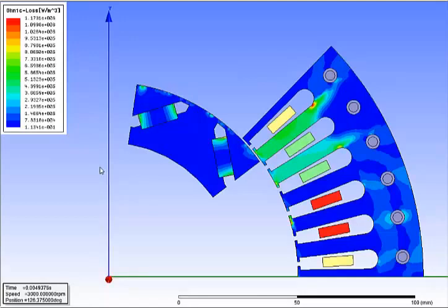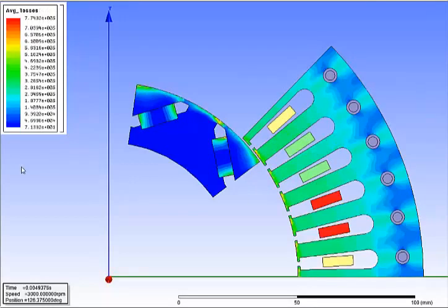Of course, the thermal losses from the structural material will be a thermal source for the fluid simulation. What we're interested in is not the unsteady thermal losses, but rather we'll time average them, extract the steady thermal losses, and use that in the fluid simulation.